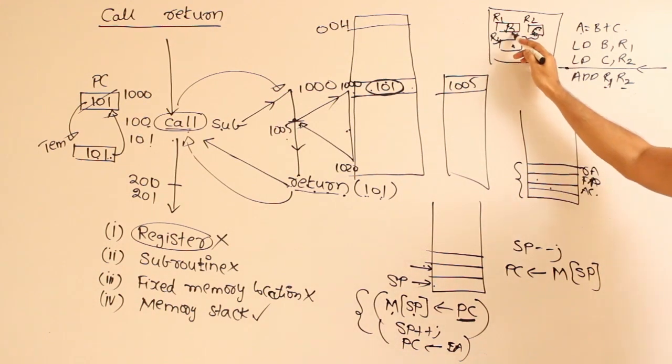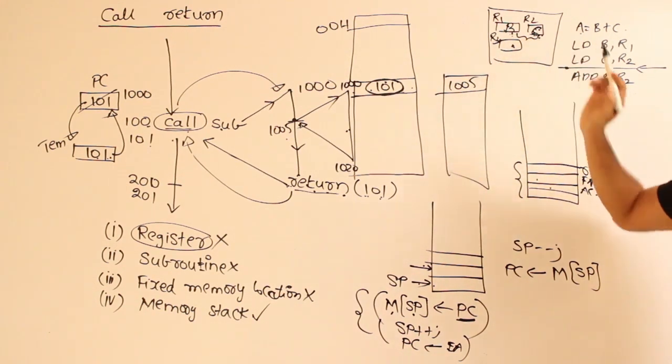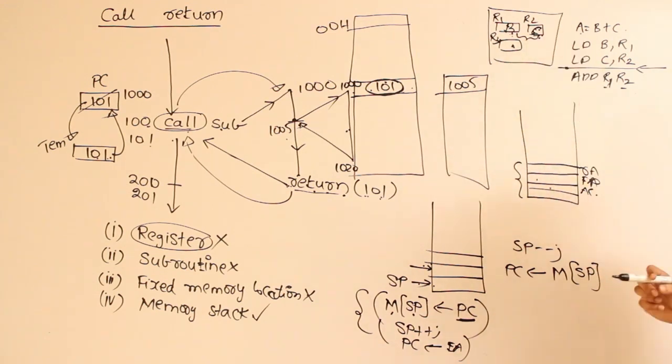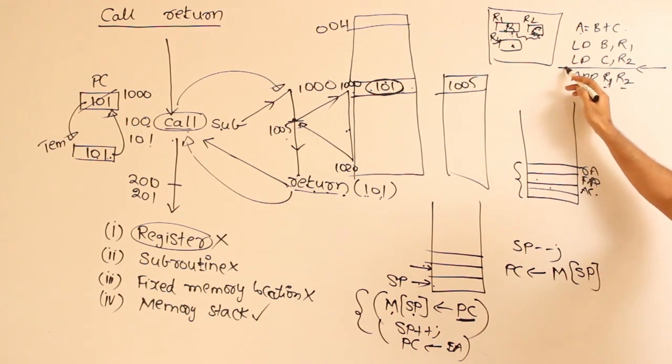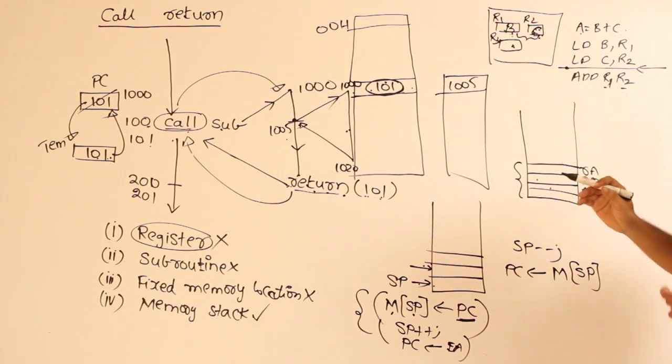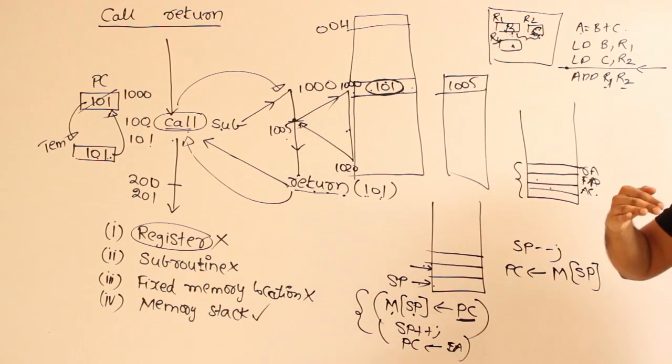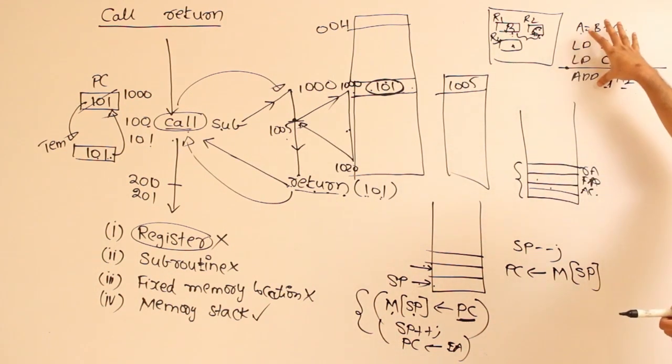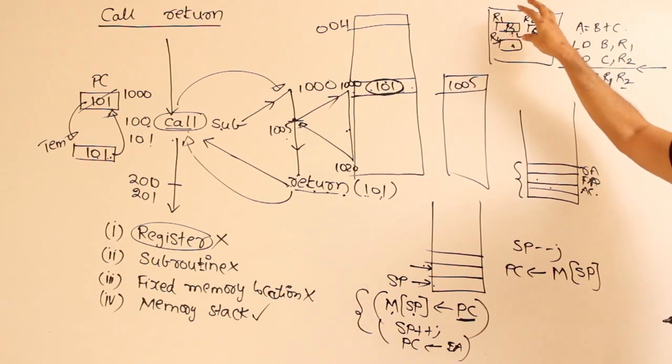In that case we are supposed to save this status, or the context. Along with the registers, we should even be saving the program status word as well, because the program status word flags might also be useful for you in the next instruction, right? Therefore when you are changing the process or the program because of some external event, you are supposed to save the context.